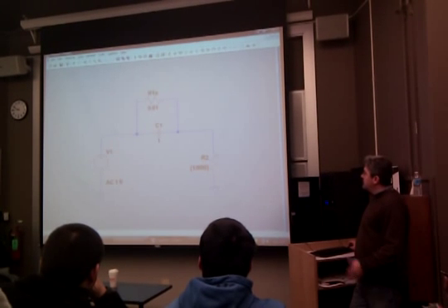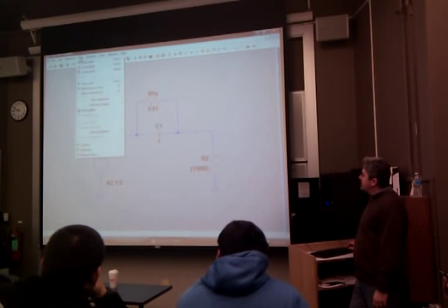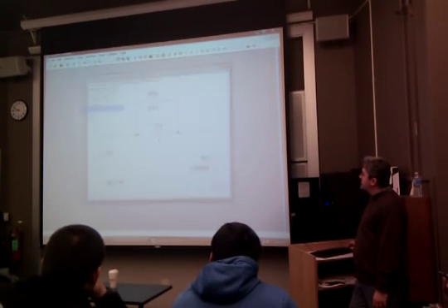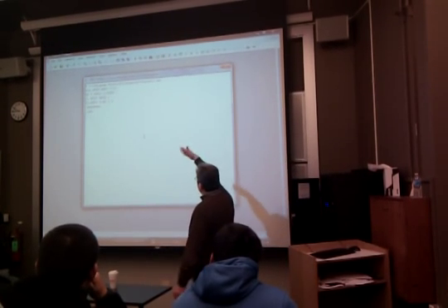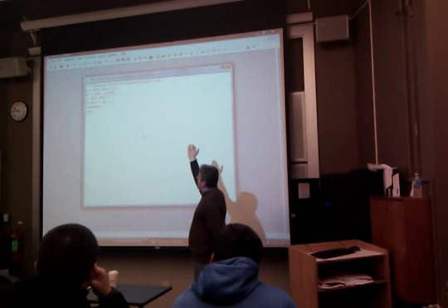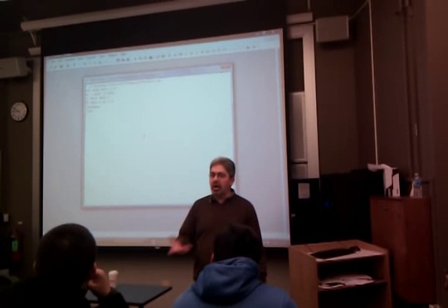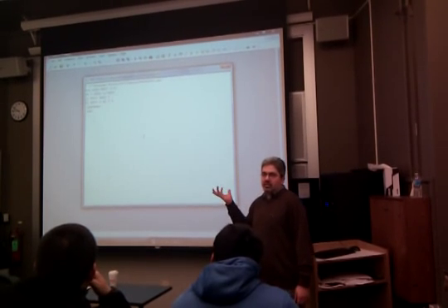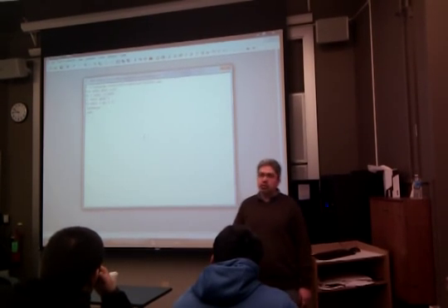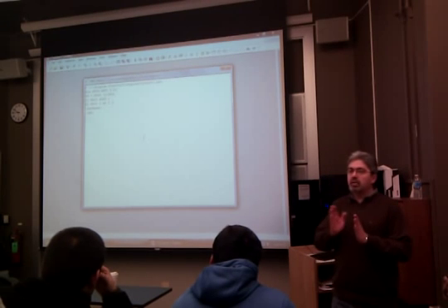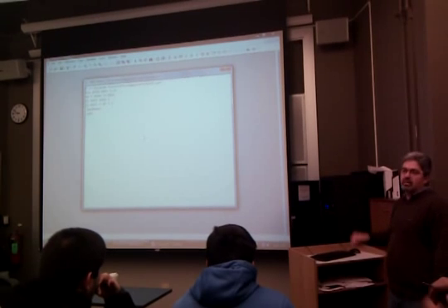So, you can go and label the terminals as well. If you don't do that, it'll just number itself. So, right now, if you look at the schematic, there's already a netlist associated with it, and if you go to View Spice Netlist, you'll see that netlist right here. R1A, etc., and the numbers at the end, like 1 over 900, are the component values. So that's what I was saying. If you go to, let's say, R2 and change it to 300, your first number will be 300. It's not the reference designator. Spice looks at the first letter to tell us what kind of component it is. Things that begin with R are resistors, V are voltage sources, C are capacitors, etc., okay?